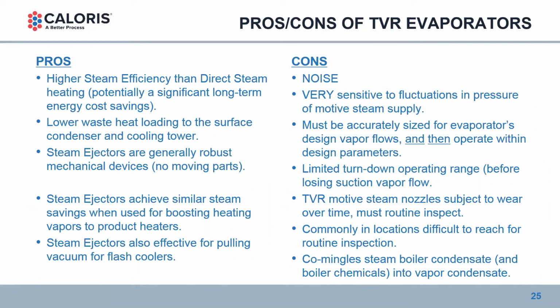They do create sound, and you can't really get around that. We can use sound insulation on the TVRs, but they're still loud. And they are very sensitive to fluctuations in pressure of the motive steam.